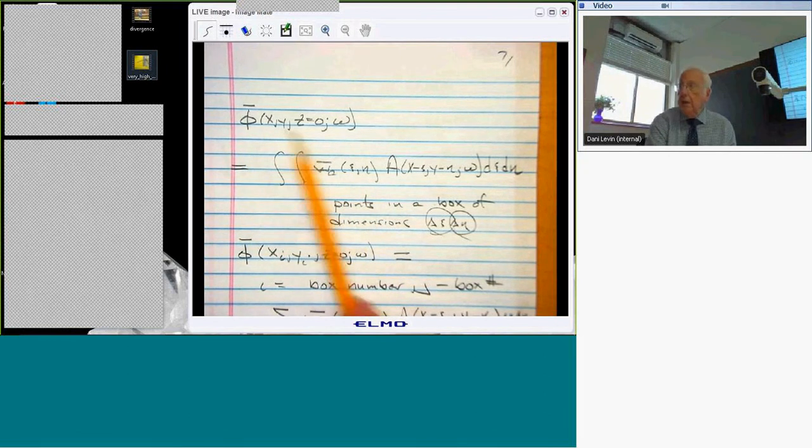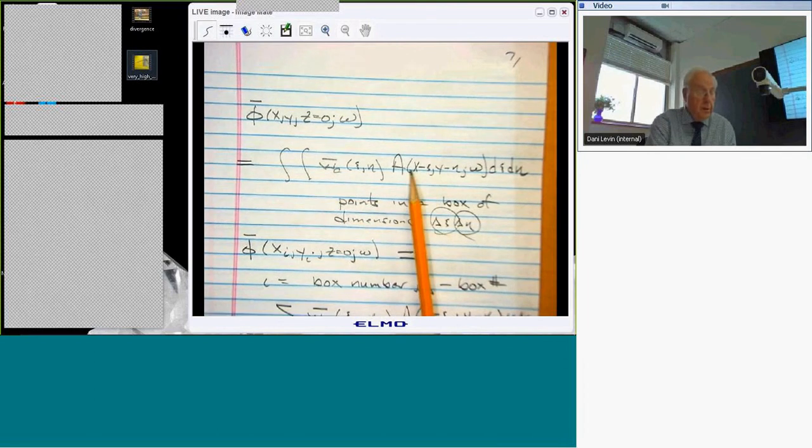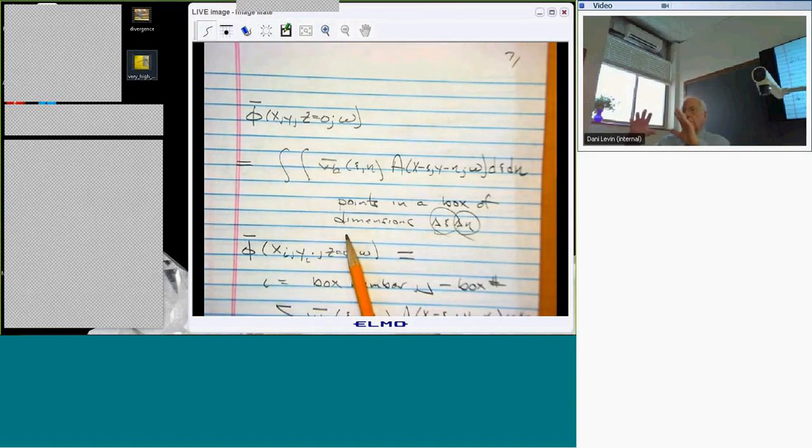In fact, you can do something else. You can use Bernoulli's equation. So this is outside, and what's inside is not phi, but pressure. And now the integral is the integral of an aerodynamic kernel function, or Green's function, times the pressure distribution, perturbation pressure. And formally, the region is still everywhere, except for the lifting problem, we know the perturbation pressure is what off the wing? It's 0. So when we put the pressure inside, the integral only has to be over the wing.